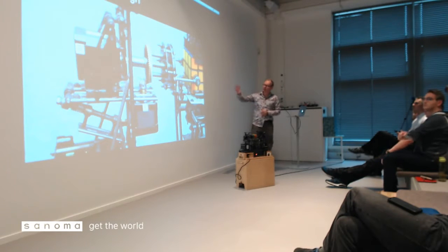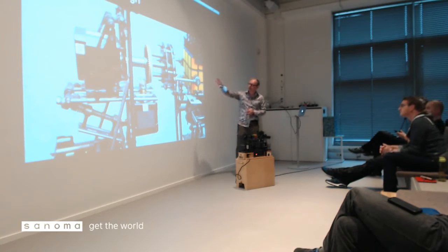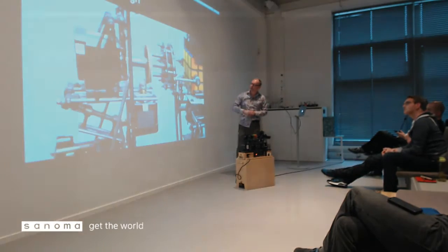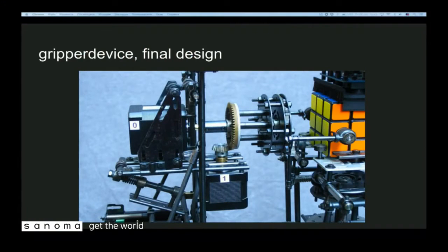And what I did is I introduced a satellite consisting of a contrate gear, which is carried by an axle from motor 0. The axle of motor 0 is all the way going through the center of the satellite, and it drives a small gear which drives the toothed gear racks.